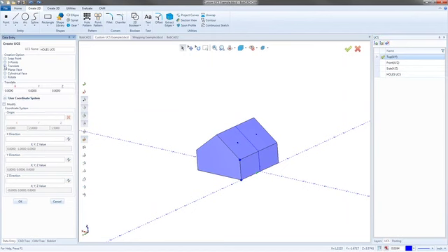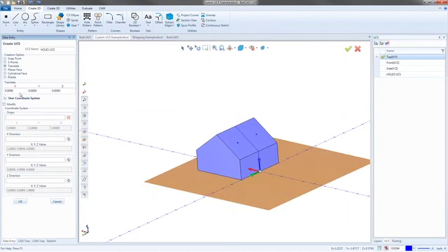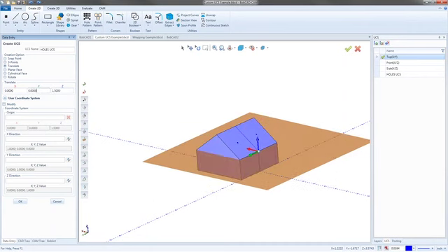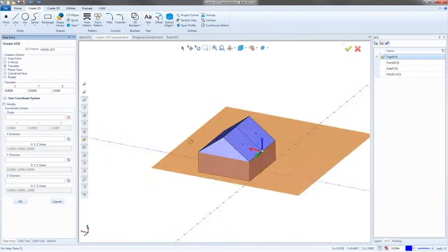If you go into the translate function, it's just going to ask you where you want to move this plane to. So we can go in and say, okay, I'm going to leave X where it's at, but I want to lift my Z up. Let's just say 1 inch. That's not long enough. 1.5. I want to go right to the bottom edge of that. That's close enough. So that's going to create a plane.